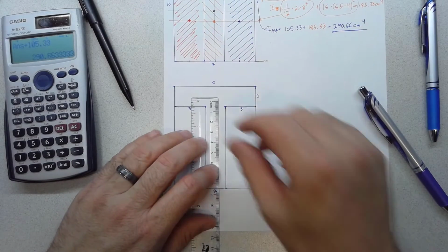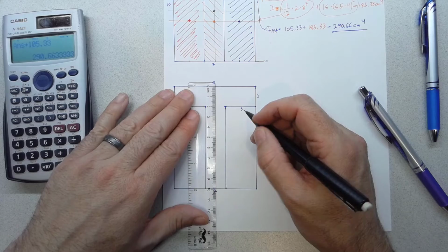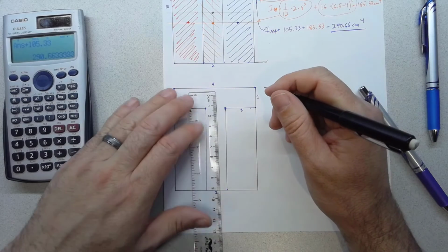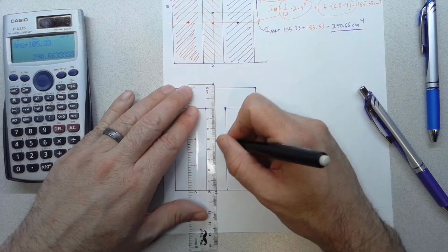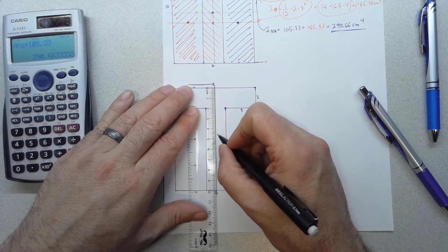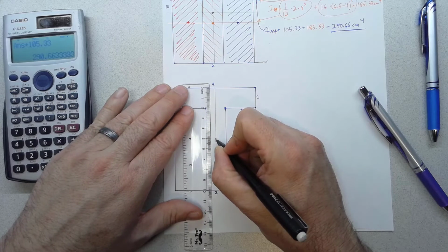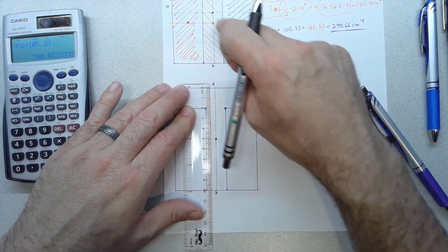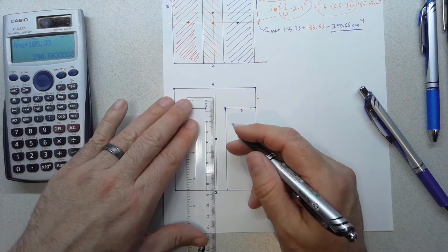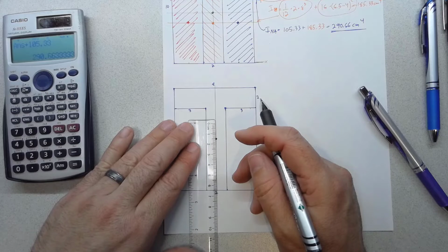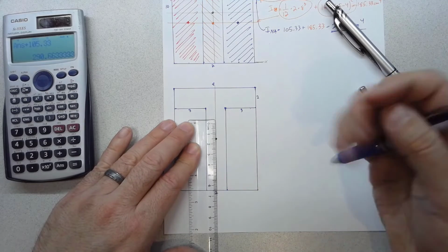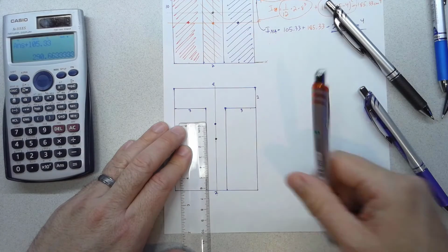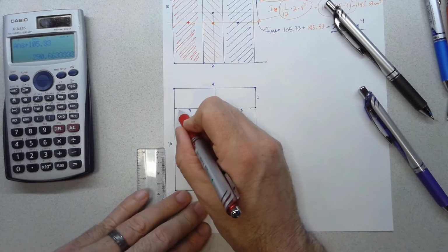Let's look at what I mean a little more closely. So we still have an axis of symmetry right here through the middle, right? If we look at it, it's over 4 in the x direction and then 5. So there's our axis of symmetry, and here at 5, that is the centroid of the whole 8 by 10, but we found that the centroid of our composite shape is actually up at 6.5. So that's that final centroid of the shape that we really want, the one that we're looking for at the end, is up here at 6.5. And then let's try to use consistent colors here.